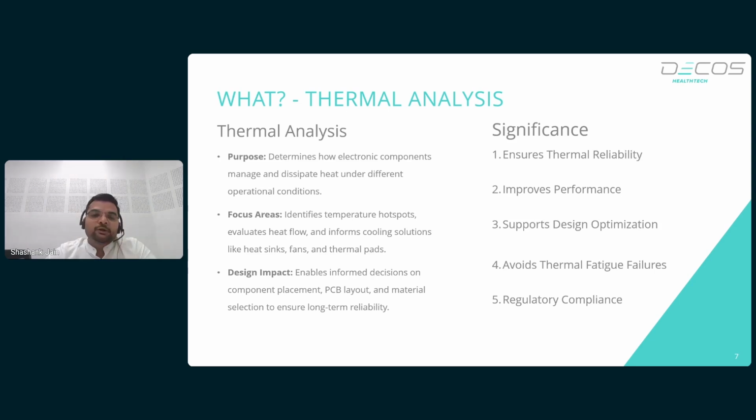Right. Again, you kill all the apps. You're done using your phone. You keep it back on the table. It comes back to the room temperature. So there is a cycle which it has to undergo from room temperature to a higher value of temperature and then comes down. Now this may happen 100 times or more than 100 times in a day. This introduces thermal fatigue in an electronic component, right? So your thermal analysis helps you to avoid these thermal fatigue failures, right?